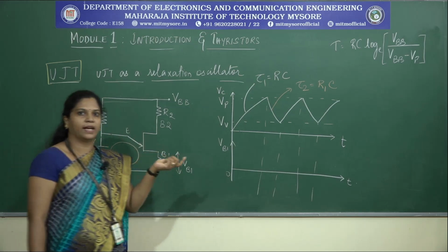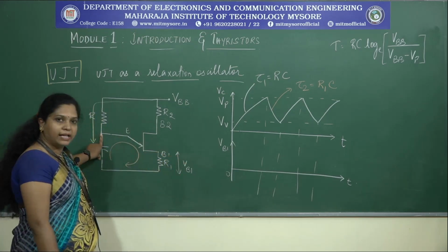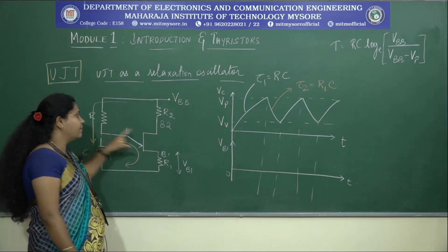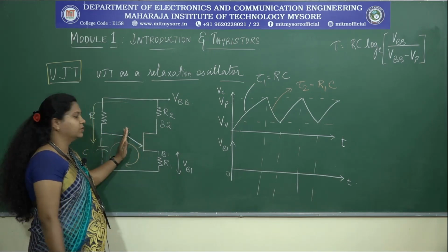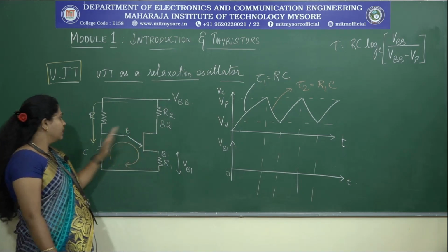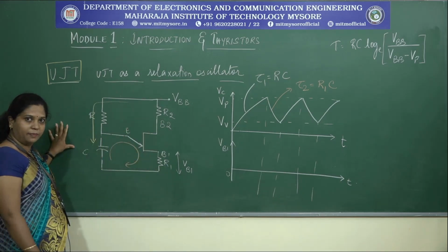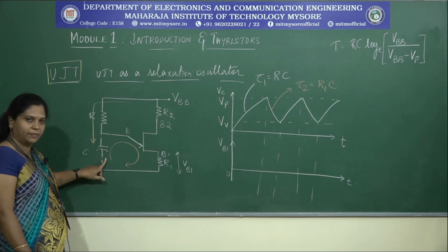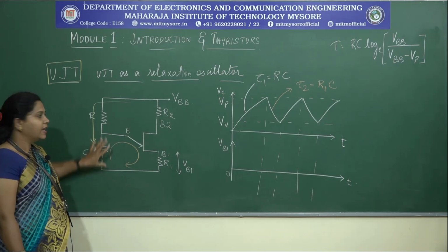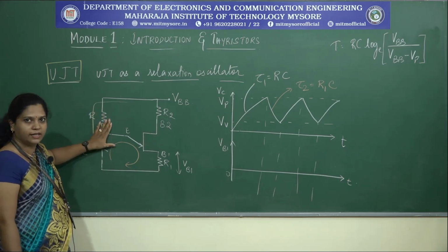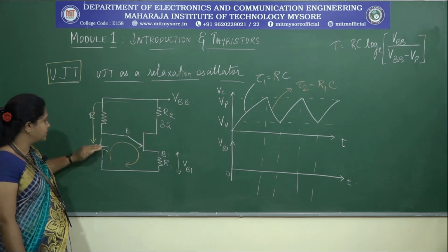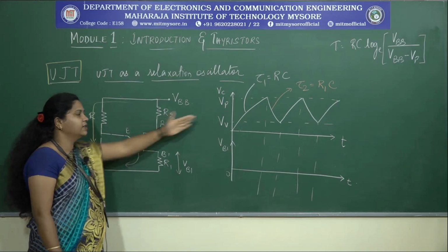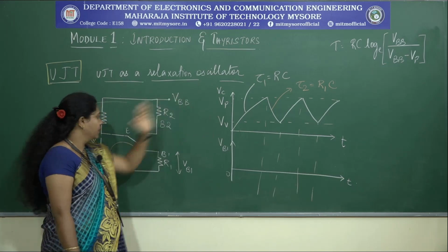Now in the biasing circuit, we were connecting a terminal known as VEE, a supply voltage, and applying it to the UJT. Here, instead of using an external supply VEE, we are going to make use of these elements, R and C, and this part is the oscillatory circuit. This C is going to produce its own waveform, and hence it is known as the oscillatory circuit.